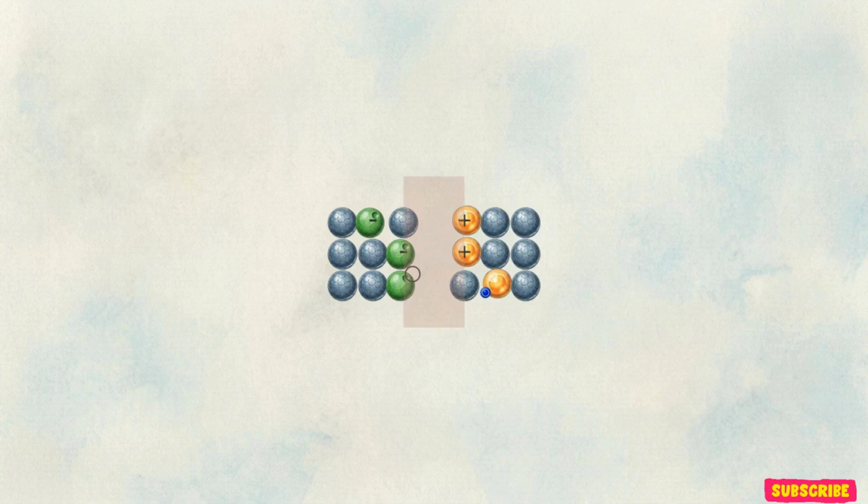The presence of these fixed, oppositely charged ions creates a strong, localized electric field vector straight across the junction. We call this electrostatic barrier the built-in potential. For standard silicon devices, it averages approximately 0.7 volts. This built-in potential acts as a repulsive force that halts any further electron diffusion. There is no physical wall inside the component. This self-regulating 0.7 volt electric field is the primary mechanism governing directional current control across the junction.